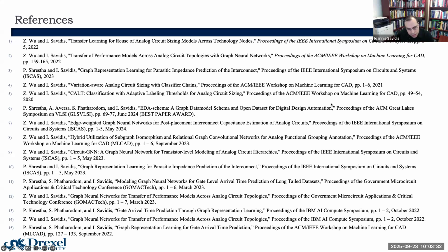The biasing conditions and sizing are what give you the class type. So you can have the topology, but you need that second aspect, which is a little bit more critical when you're designing power amplifiers: the biasing conditions, and whatever the variability conditions or constraints that you need to design for. So yes, we generate, but there are other algorithms that have to run on top of it to make sure that you meet the constraints and specifications. Thank you.